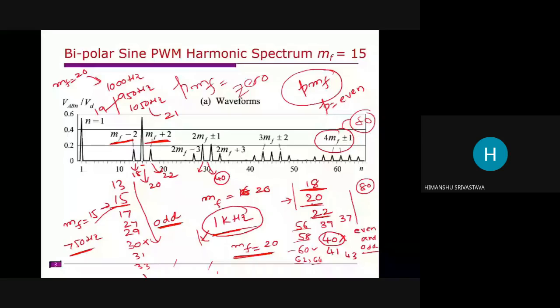You multiply the actual signal by -1, and you will get a negative signal, meaning the opposite signal. The sine wave is the normal signal; if you want the opposite, you just multiply by -1. Digitally, it is easy. When implemented in analog, one simple way is to interchange the terminals. If you interchange the terminals, obviously the polarity will be changed.